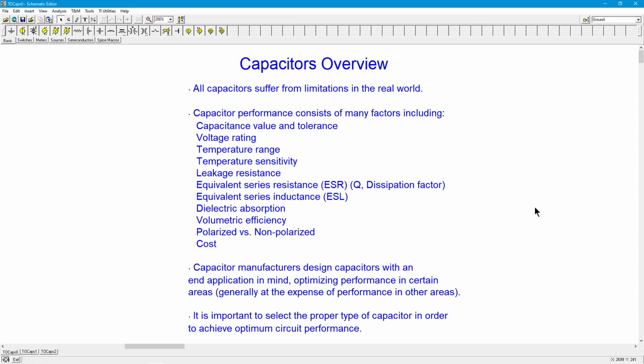In other words, it can rebound back up to 50 volts. Clearly, that could be dangerous, right? I mean, in general circuit work, that might lead to things like distortion, if you had an audio amplifier or something. But I think, okay, that's not good, but something that's dangerous, like you're getting this high rebound voltage, that's worse. So that's one reason why you might see a large value resistor across particularly large filter capacitors, for